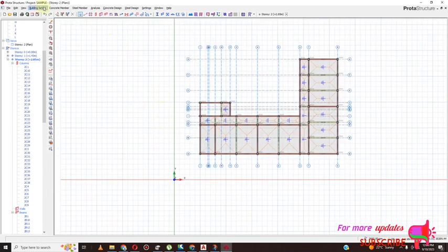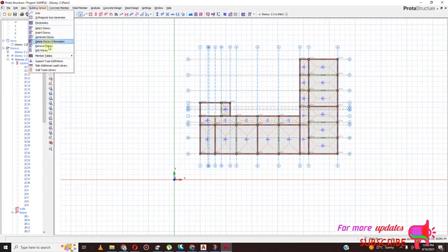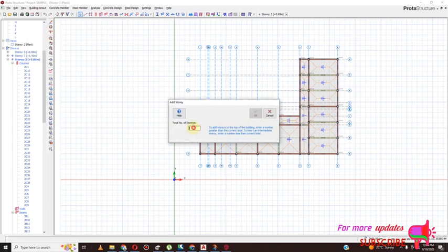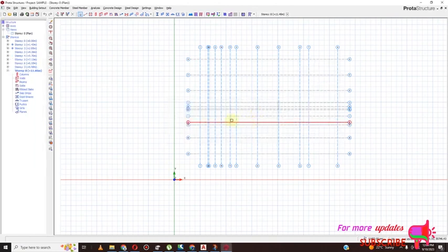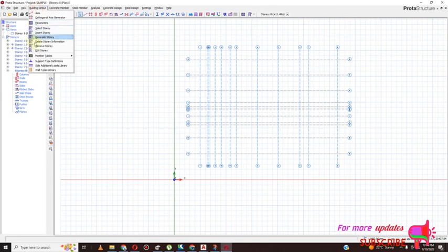Now we can go to building and insert stories. They are now going to be 8 up to the last floor, and then the other floor will be the water tank, which will be the 9th floor. So okay, I've inserted 8 more stories. So I need to edit the stories.